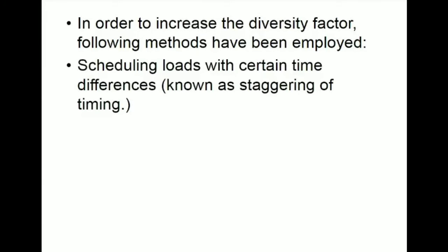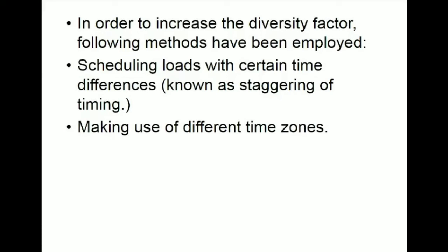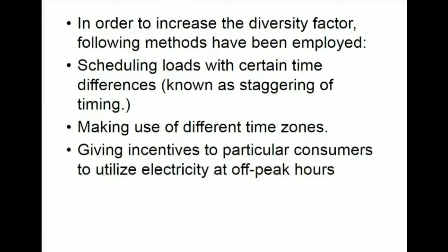In order to increase the diversity factor, the following methods have been employed. Scheduling loads with certain time differences, known as staggering of timing. Then making use of different time zones for different types of loads. Giving incentives to particular consumers to utilize electricity at off-peak hours.